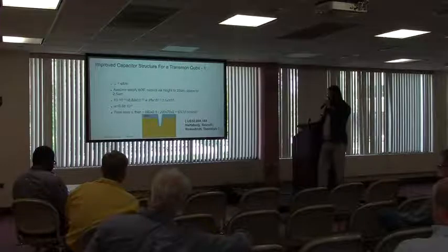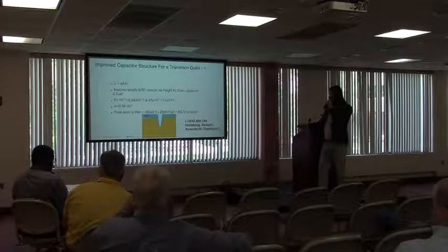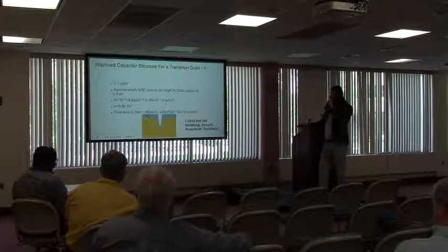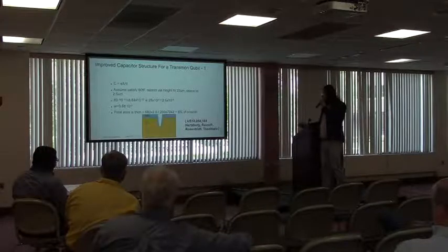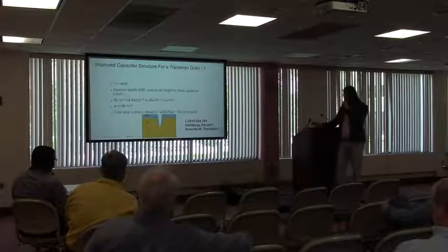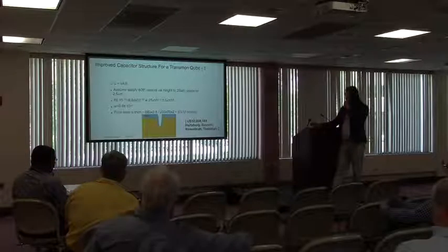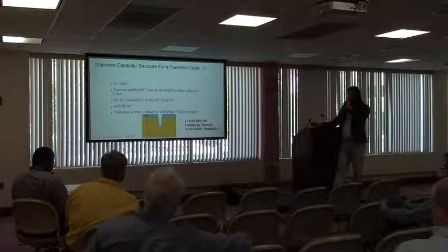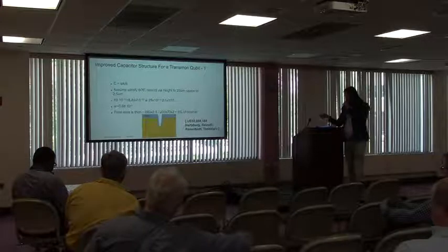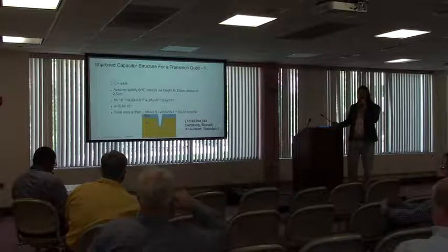So assuming this niobium is our superconductor, we tried going into the silicon to form our capacitor. So it's going to couple a bit through the air, but a lot of the coupling can also be through the silicon as well. And when we went through these formulas, we noticed that we are able to reduce our area of this capacitor to 6% of the traditional flat capacitor. So we have described our structures in this patent, for example.